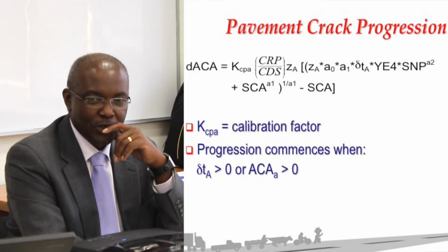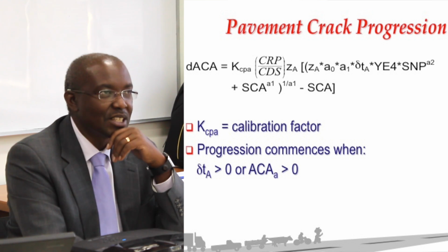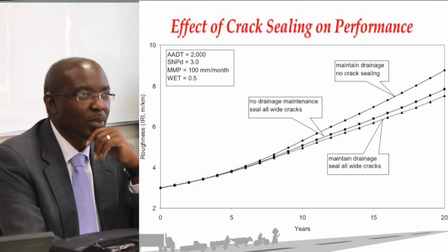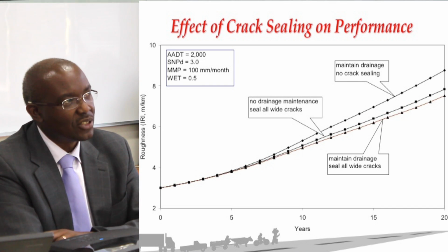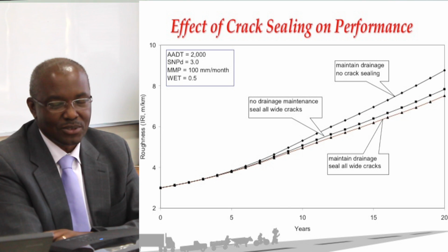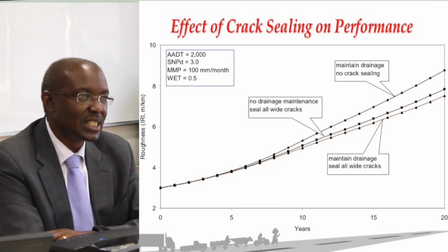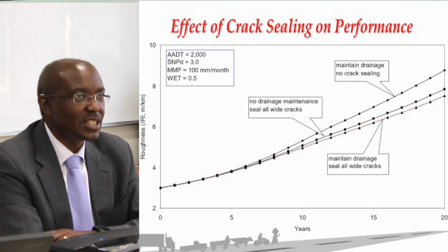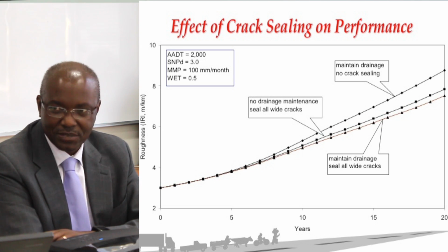Roadworks would have the opposite effect to deterioration, as you might expect. If you apply maintenance, then you slow down the rate of deterioration. Here we're measuring deterioration in terms of riding quality, of something called roughness, which is actually a technical measure of road condition. The higher it is, the poorer the road condition.